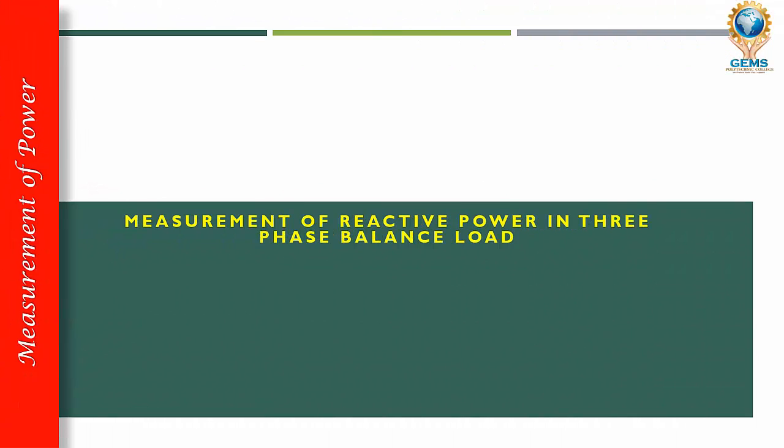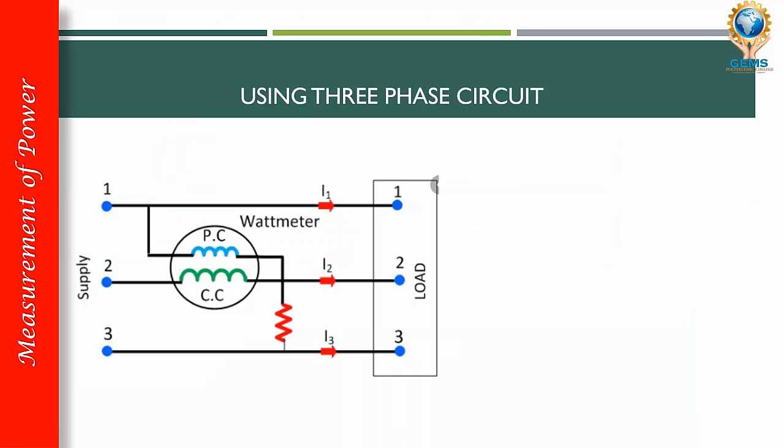Hello everyone, today we'll see how we can calculate reactive power for a three-phase circuit, for a polyphase circuit and for a single varometer circuit. So first we'll see how we can measure reactive power for a three-phase circuit. So reactive power is given by the expression, reactive power is represented by Q. So Q is equal to Vi sin phi.